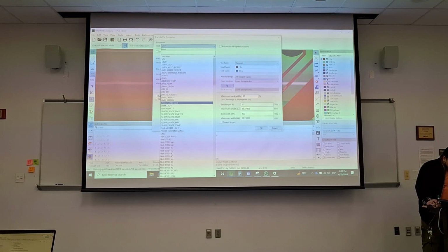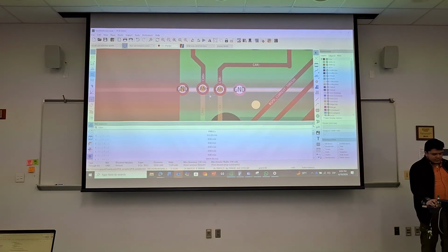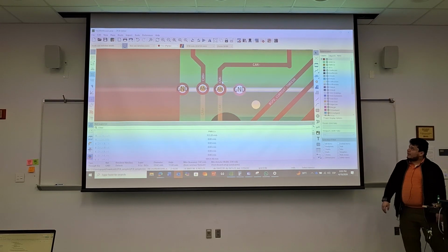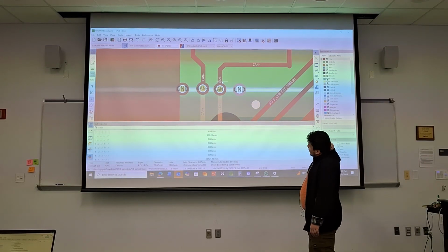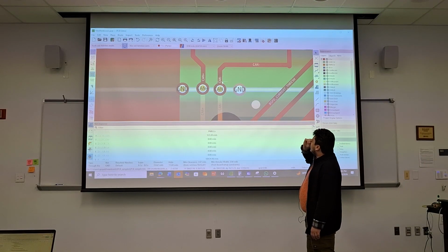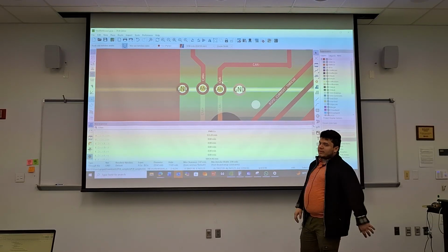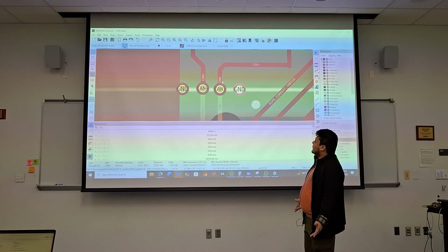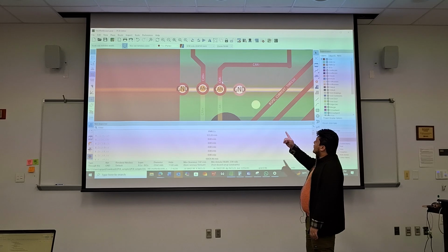But yeah, so shielding is not too crazy with this. That is more than enough shielding. If you do have differential pair transitions, just having ground vias on each side is going to help your signal a lot. Because sometimes people forget to do that, and it degrades the signal quite a bit. So doing that helps a lot.